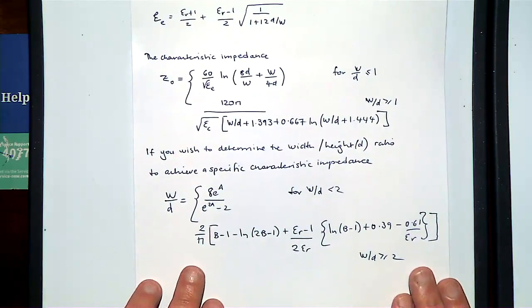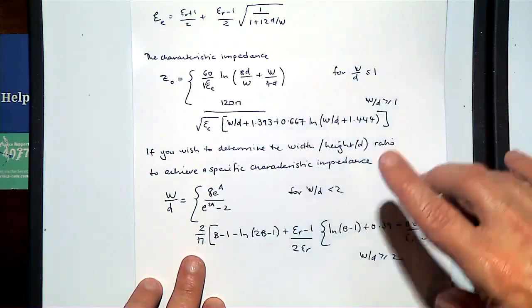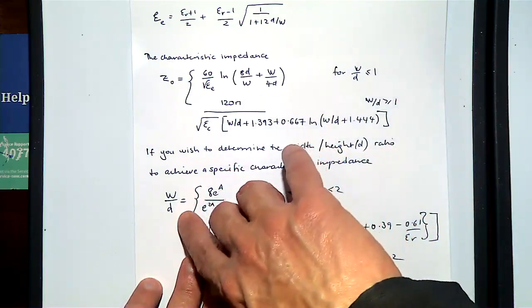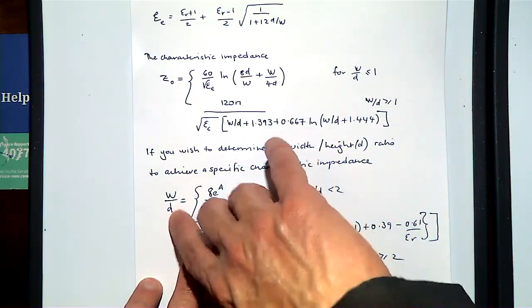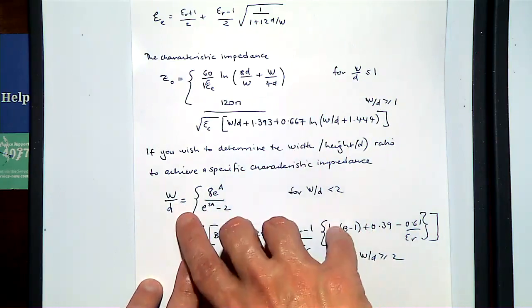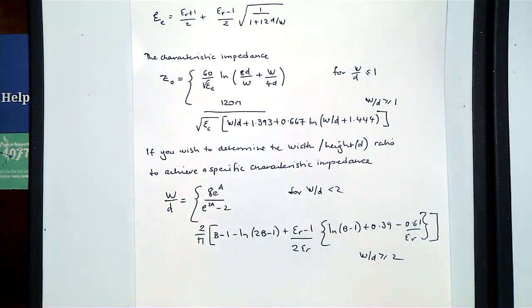And essentially, we determine the width to the thickness of the material. And usually the thickness of the material, for all of you that have seen or designed a PCB board or designed a chip, the thickness of the layers is predefined. Or you may have some flexibility, but you don't have arbitrary flexibility in designing the thickness of those layers of dielectric, right?